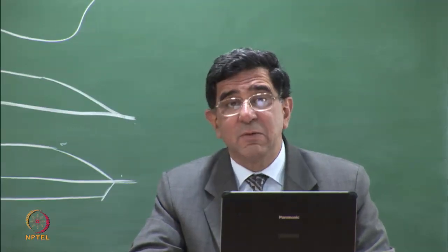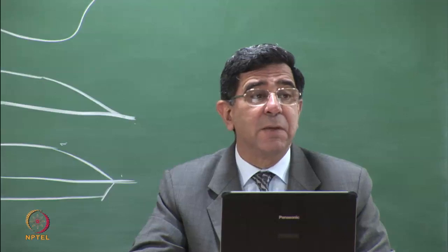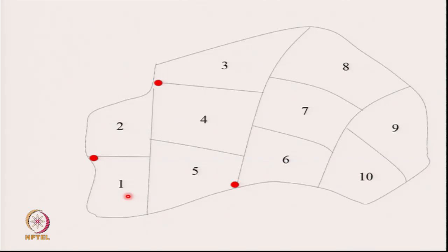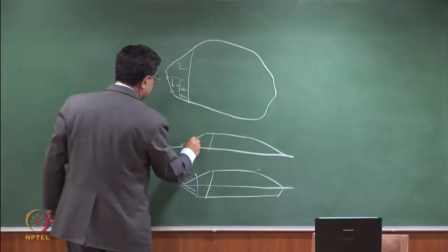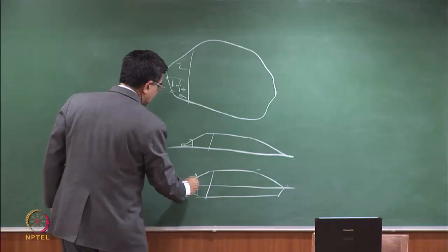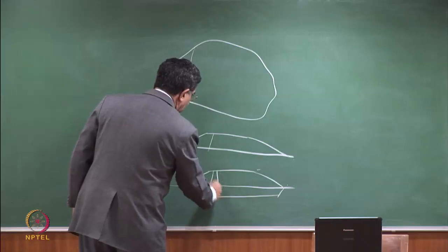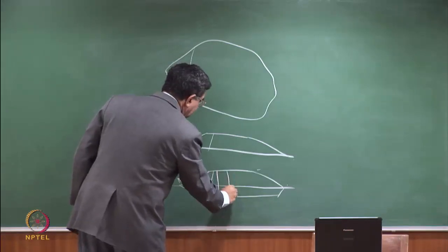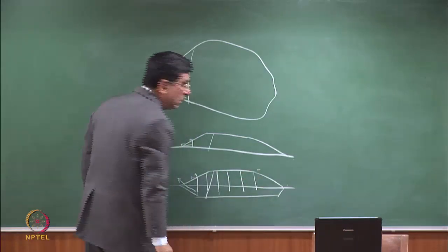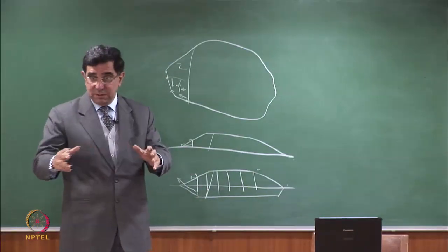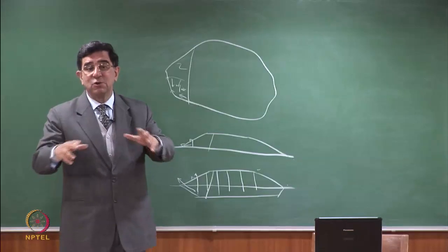The wells are at the center because you put the wells at the maximum depth of waste. So if you were to put a well at the side, here, I don't even need a well here. I don't like to put a well here, but this is the maximum height, so you tend to put the wells at 2/3 of the depth of the waste, where the waste is at a maxima. So your gas wells will be at a spacing of 50 to 75 meters towards the center.